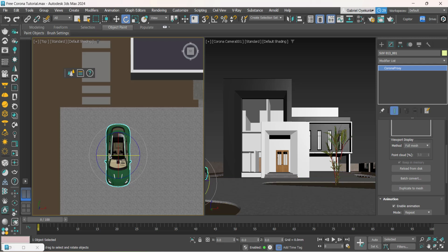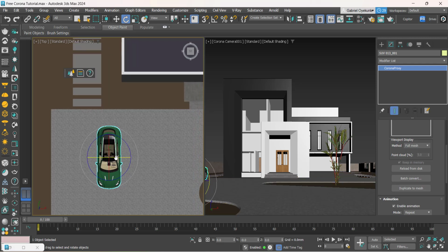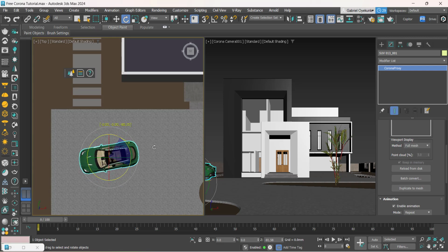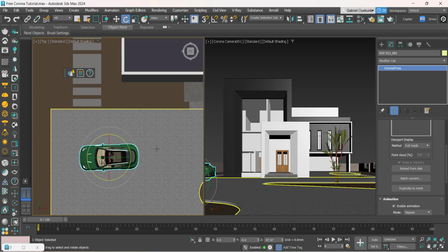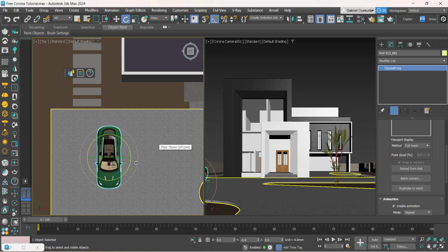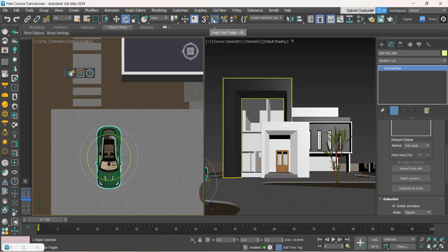So now right here, you want to rotate, and you are going to press either E on your keyboard or click the rotate tool here. So I pressed E on the keyboard and I can rotate, and as I'm rotating, I'm seeing some figures around here, which are the degrees at which I'm rotating. And if you want a perfect degree, you press A, which is this angle snap.